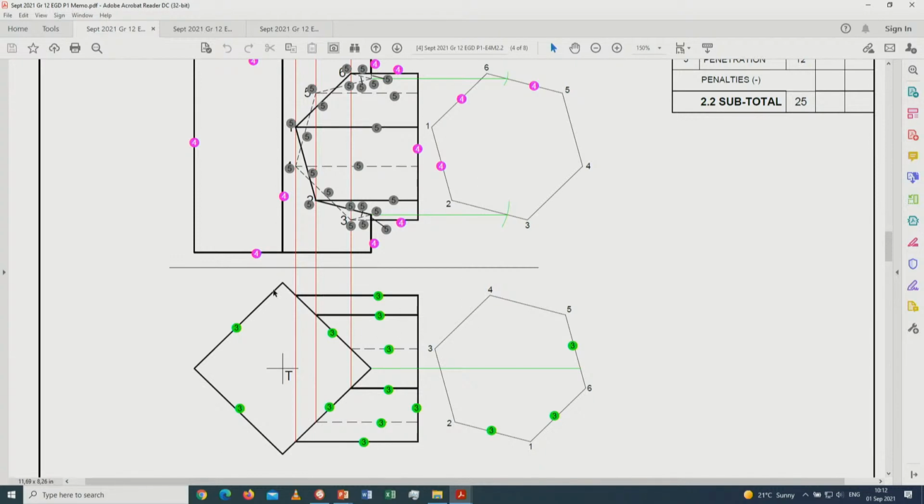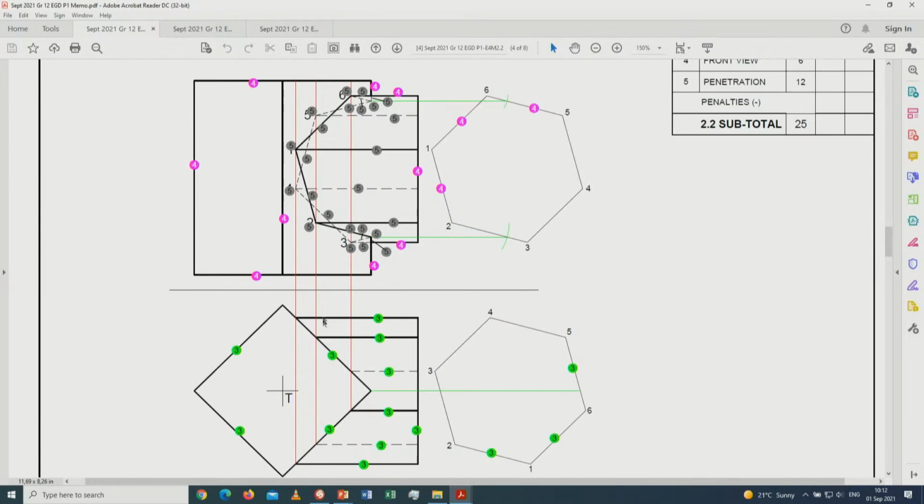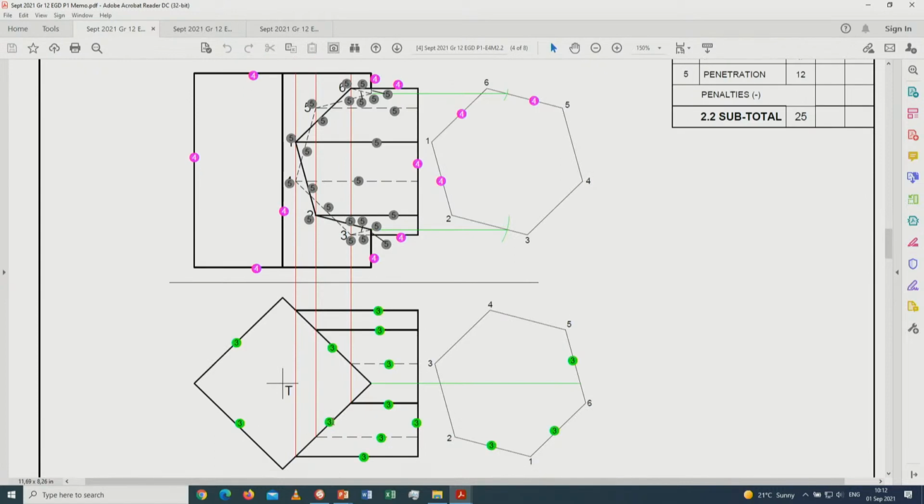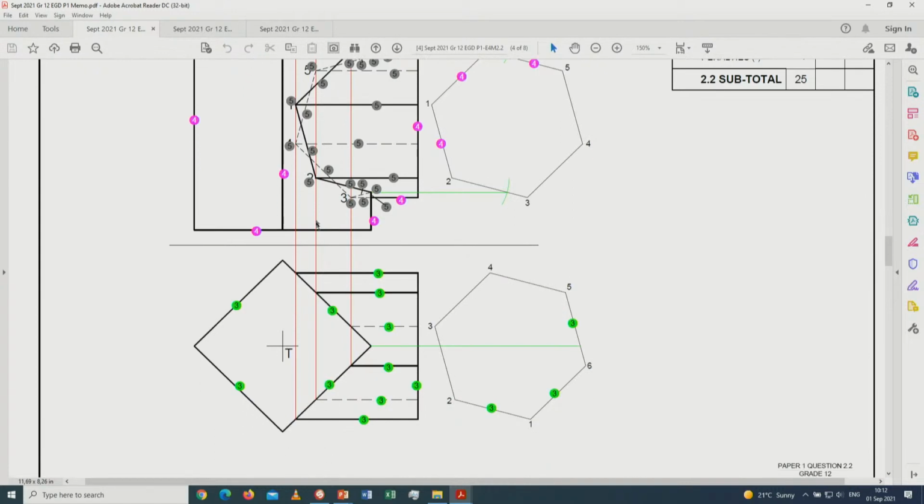All right, if I go to the answer of this question, that means in this case all the lines need to be extended to find those points, and then of course the rule applies in terms of, I used to say to the learners, if you take from the bottom and have a look at it from this point, I will see this line, I will see that line, and I will see this hidden detail line from the bottom over here. So those will be dark lines. So if I extend this line up to the end, I will go all the way up, and then from there on I will be able to find that as a solid line. Then of course the bottom line is this line over here, so therefore that will be solid.